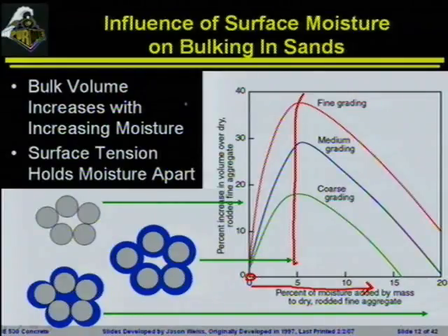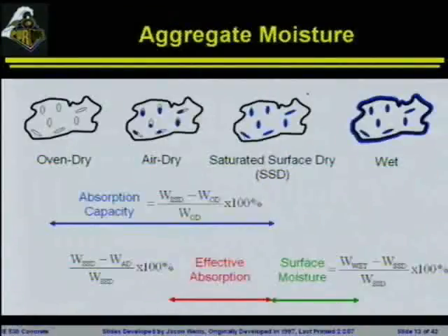In some states, it is very common to buy that anti-skid stone based on volume. So what do you think every producer does? Adds water. They add water. So much like a very fine sod that you put out in front of your house, you will find producers out there watering their aggregate, because if someone's buying it based on volume, they can make more money off of their aggregate by fluffing up the overall system. Okay.